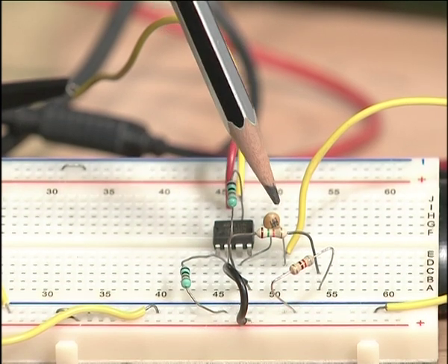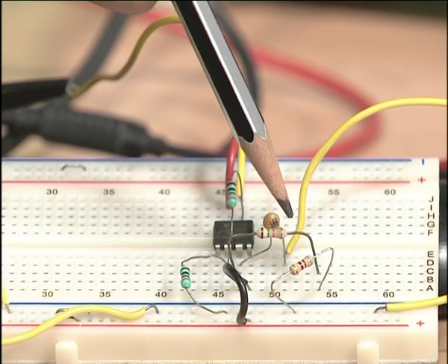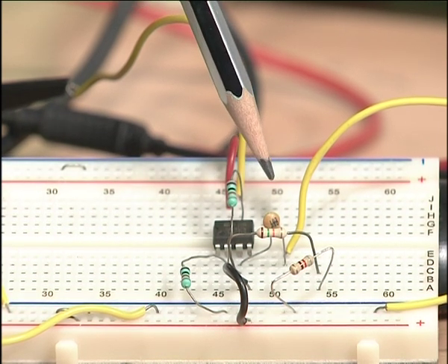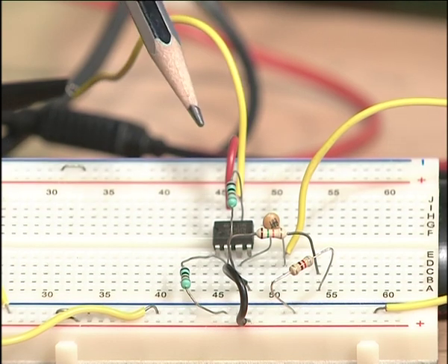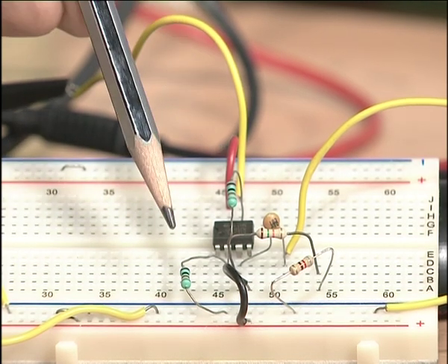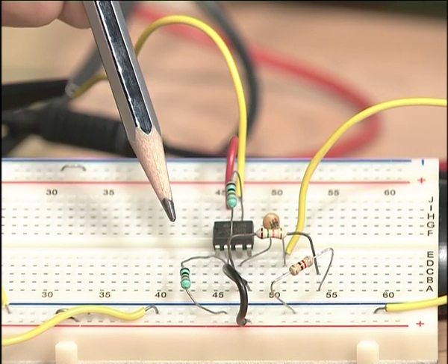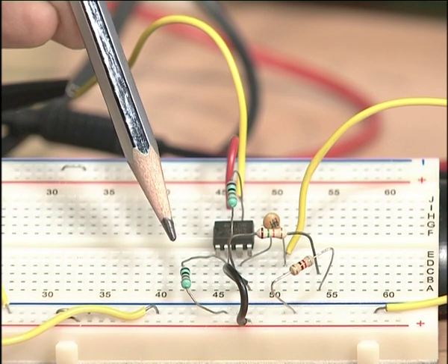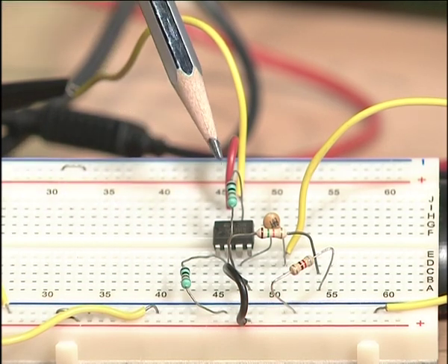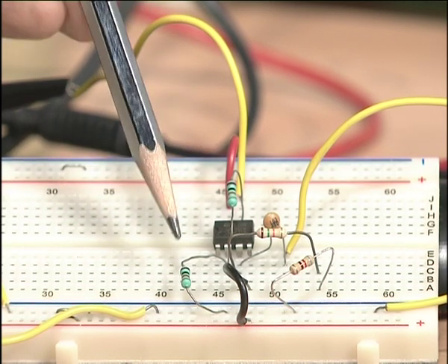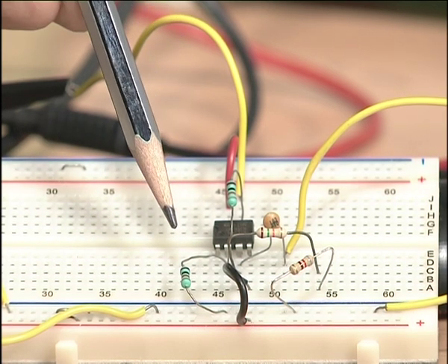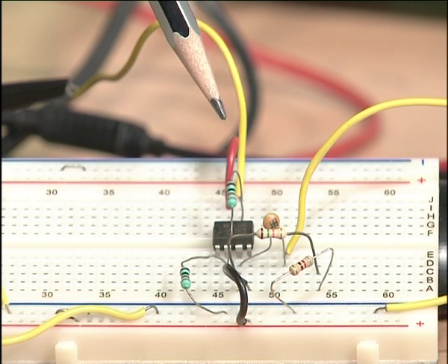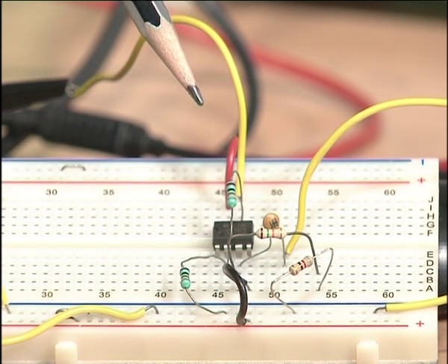So, therefore, these two resistances are with a value of 15.9 kilo ohm and this capacitance is of value 10 nanofarad, and the resistances here which are RF and R1, these are chosen for a gain of 2. So, this is with 10 kilo ohm and this resistance is with 10 kilo ohm. So, with RF and R1 as 10 k, what we get is a gain of 2 from the op amp amplifier, which is configured as non-inverting configuration.